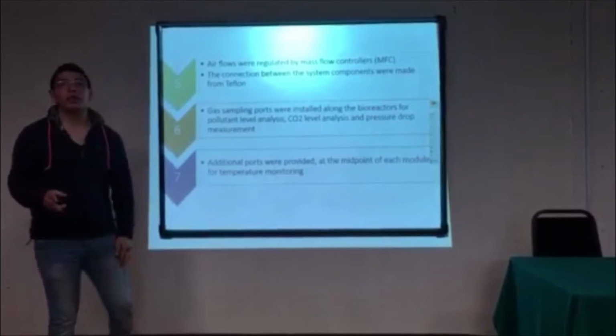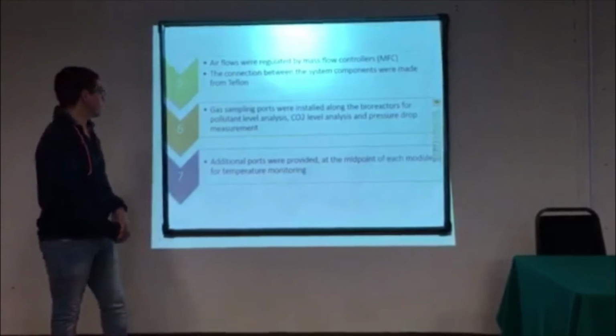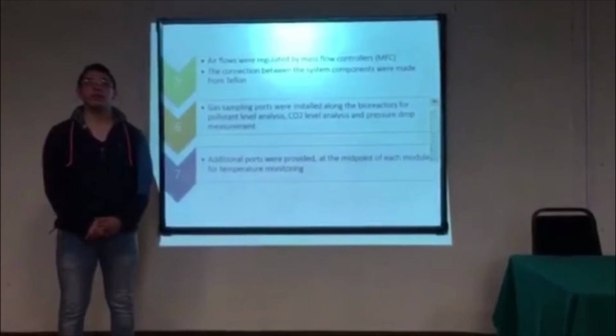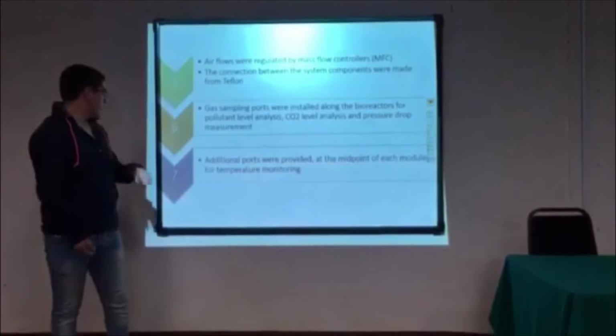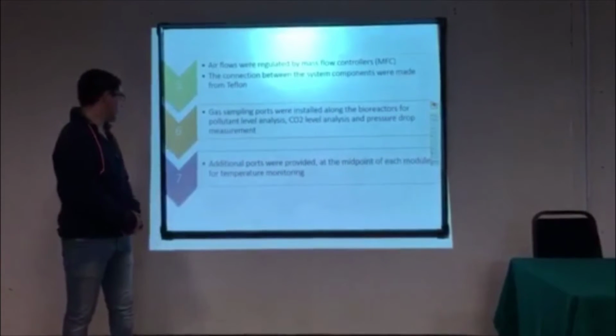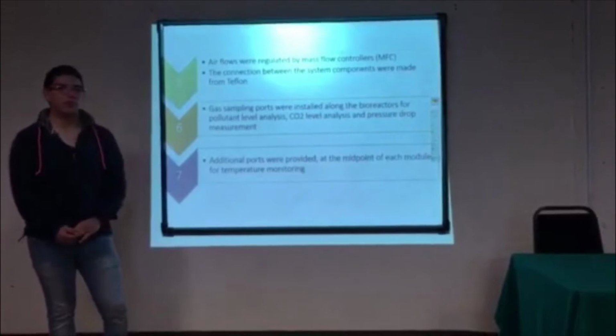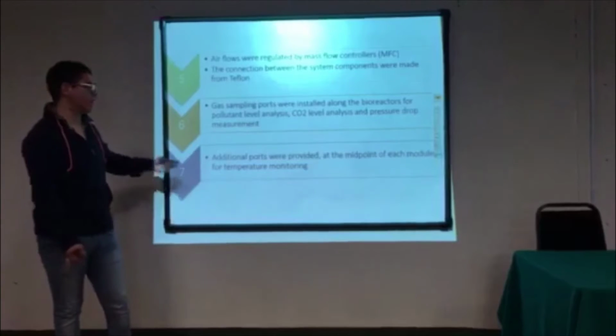the connections between the components were made from Teflon. Then the gas sampling ports were installed along the bioreactors for pollutant level analysis. And in the last part, additional ports were provided at the midpoint of each module for temperature monitoring. This I'm going to explain in the next part.